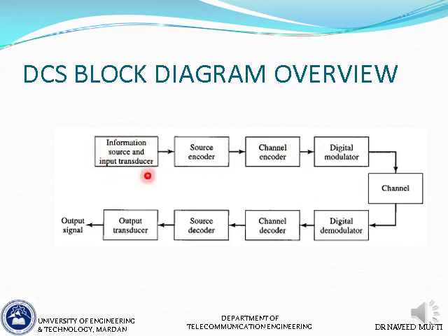So basically here the information may be analog, and then it is converted to bits. So here the number of bits are reduced or encryption is done, and then here the number of bits are actually increased as we are adding more parity bits. And then here those bits are used to modulate an analog carrier when talking about wireless communication, and then that analog carrier is modulated, so it is sent through the channel, and we have a noisy channel.